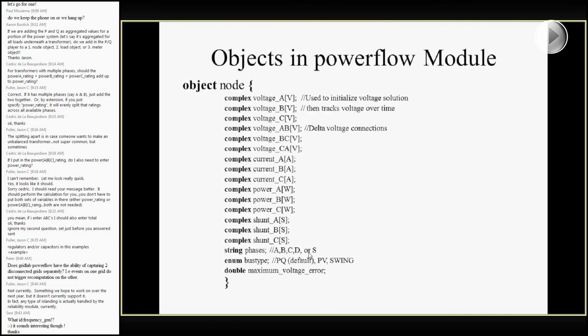It's really good if you wanted to do a proof of concept to show, maybe, what we call grid-friendly appliances or grid-friendly controllers, appliances that respond to frequency. It's a very good way of doing just a proof of concept. Beyond a proof of concept, I would not take it with that model. And like I said, it's a simple approximation of frequency, and it is only the fundamental frequency. It's only the 60 hertz or the 50 hertz, depending on your system. It won't do any harmonic analysis or anything like that. None of that should even be implied in there.